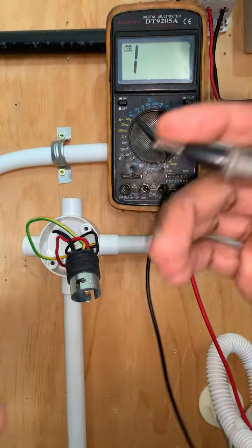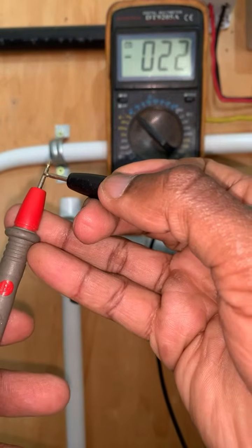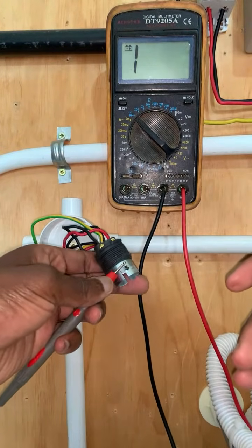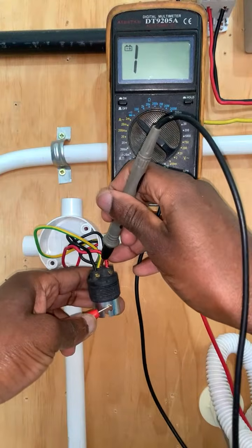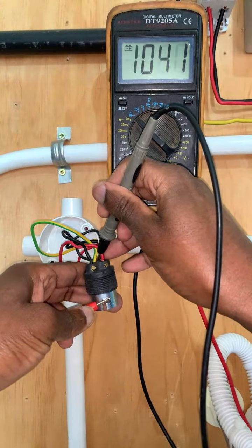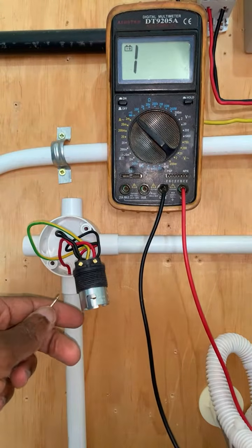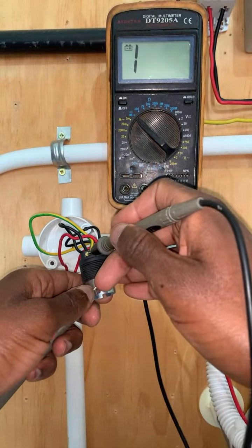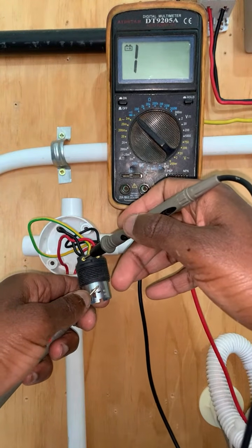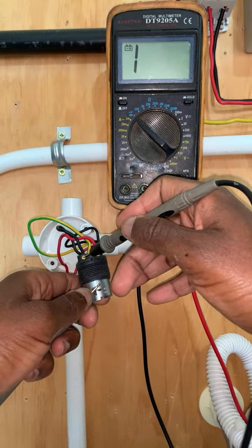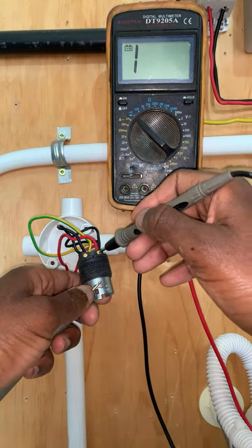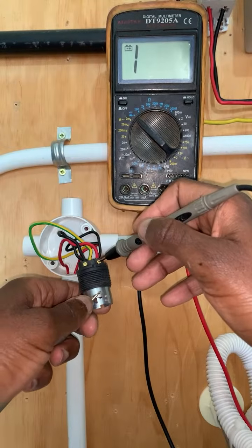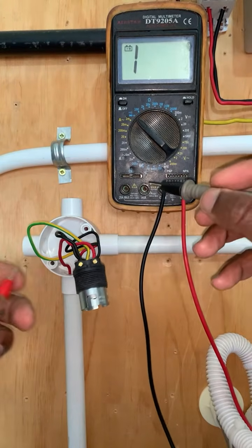I think I need to also charge the battery of that multimeter. You see? If I get a beeping sound when I place one probe on this section here and on this earth connection, definitely it is continuous, so that is correct. If I place a probe on this earth connection, or this metallic part, and the other probe on the neutral, I expect a 1, meaning they are not short circuiting or continuing. If I do the same for line, it is a 1, or simply put, infinity. There's no continuity, which is the correct result.